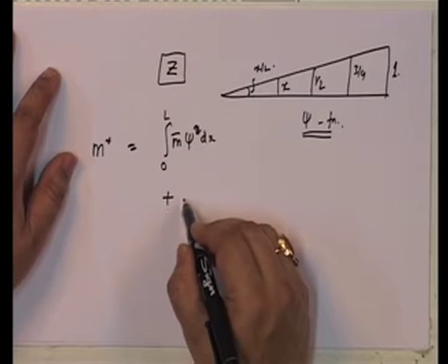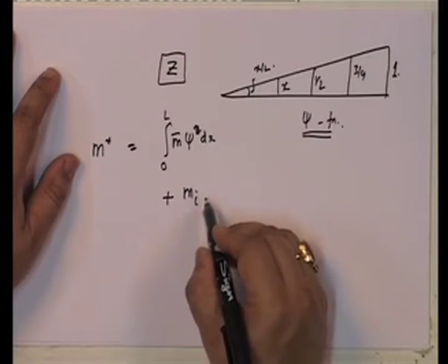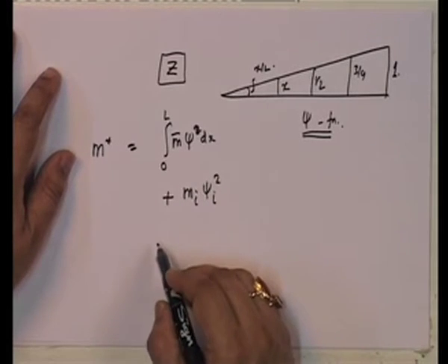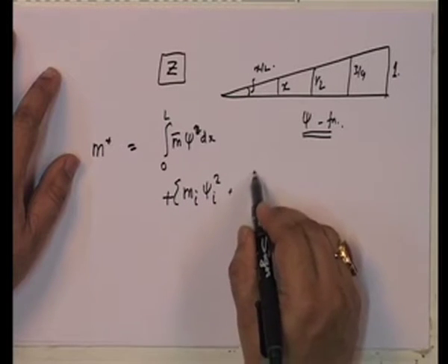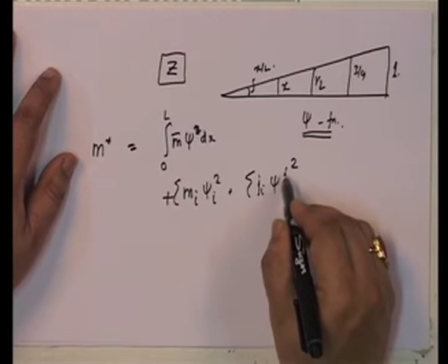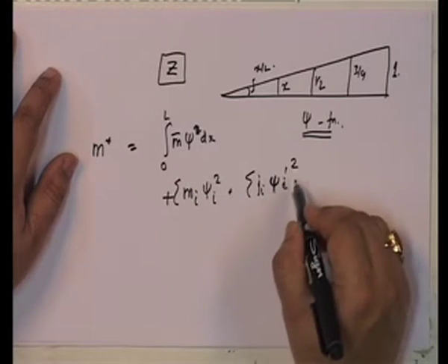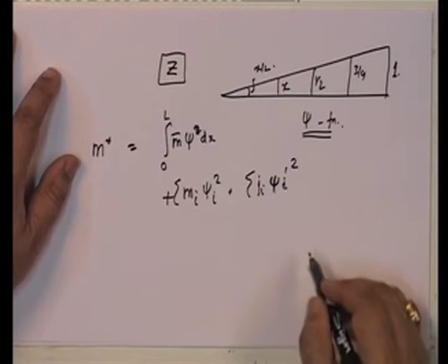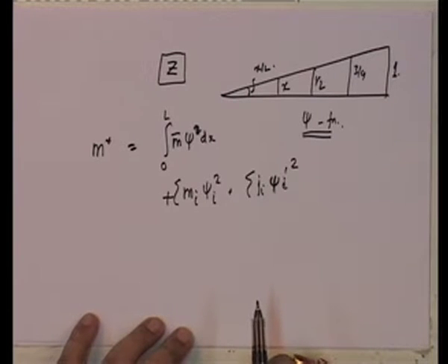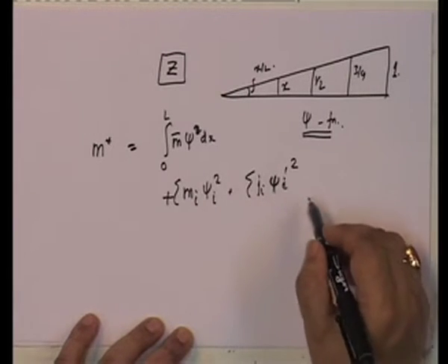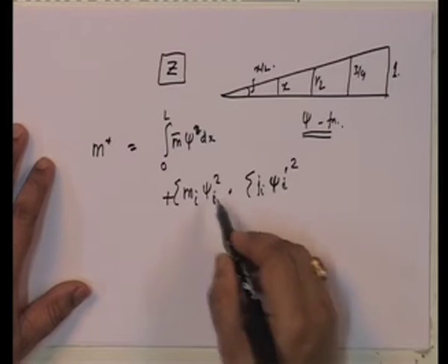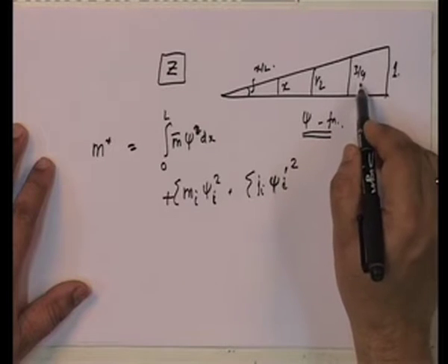If you have a linear mass, any mass m I is going to be multiplied by whatever is the xi I squared at that particular point. If you have mass moments of inertia, you just need to take the slope at that particular point squared, and in a sense you essentially land up having that m star. All you need to do is find out the shape function, find out those values.